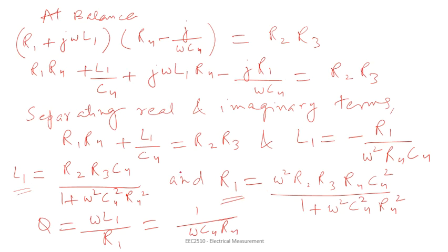Now from these balance equations, one thing we must discuss is that both these terms, L1 and R1, have this frequency term in their expression. So it means that the frequency must be accurately known before carrying out the calculations.